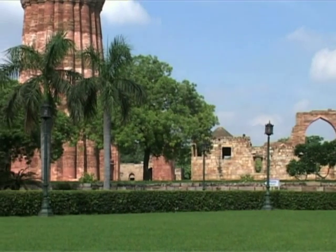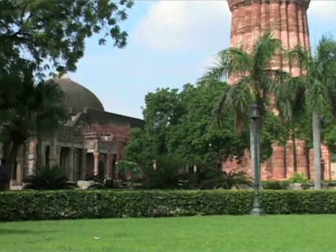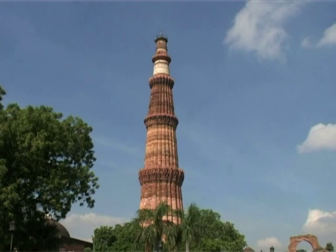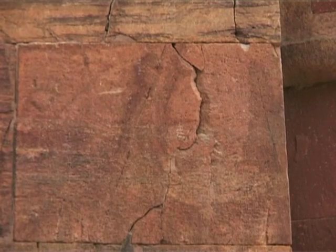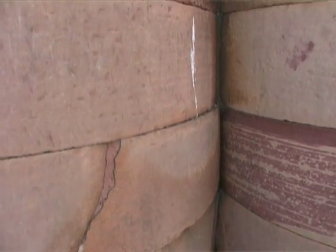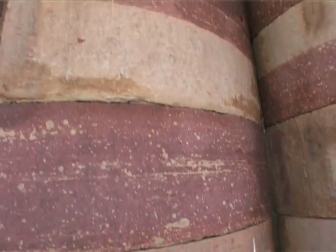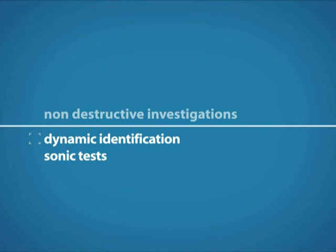The first step of the analysis for the preservation of monuments consists in the execution of a sound investigation campaign to obtain detailed knowledge of the structure and materials. With this perspective, after gathering information on the history and the present-day damage, several non-destructive tests were carried out on the Qutub Minar, intended to define the dynamic behaviour of the tower and to characterise the masonry conditions. Non-destructive investigations consisted of dynamic identification and sonic tests.